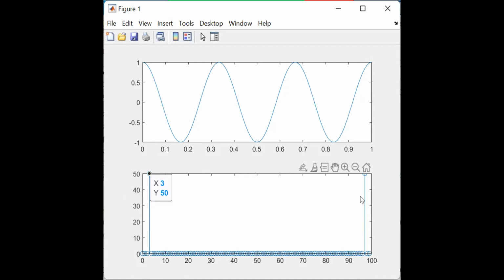Wait a second. Now, who is this guy? Well, there is some mumbo jumbo about this Fourier transform. One thing I would say: if there are 100 samples, you only see from 0 to 50. If my sampling frequency is 500, you only see 0 to 250. Neglect the second half of the Fourier transform. Concentrate only on the first half. Now let us go back.